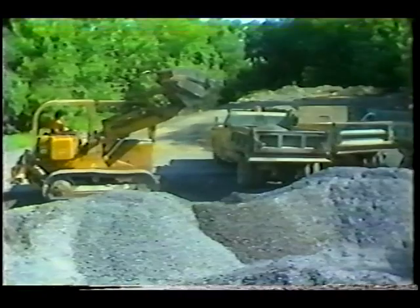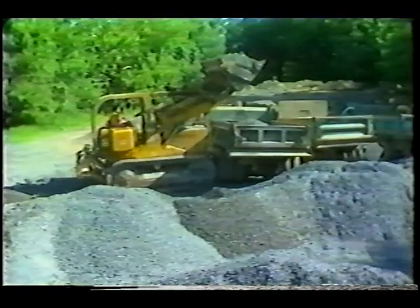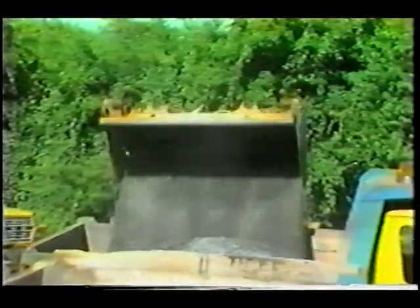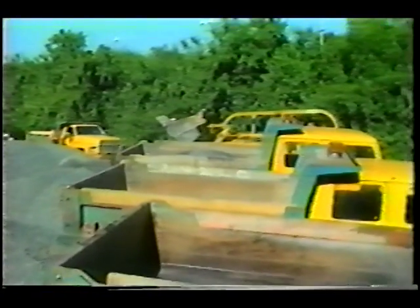It is also important that all the aggregate needed for a particular project be on hand or readily available before starting the operation. The number of dump trucks needed to haul aggregate depends on the haul distance from the aggregate to the work site and the productivity rate of the spreader.